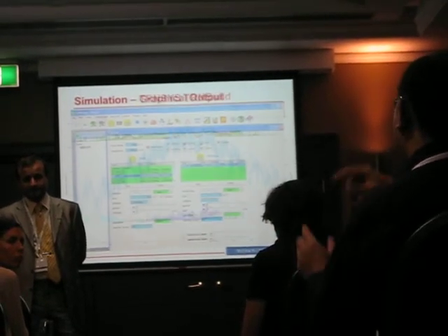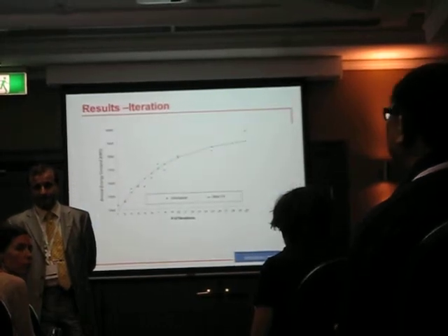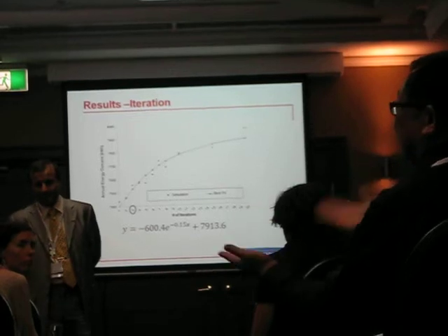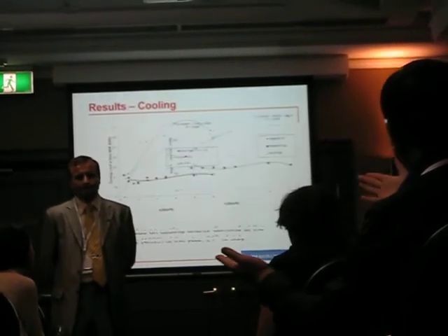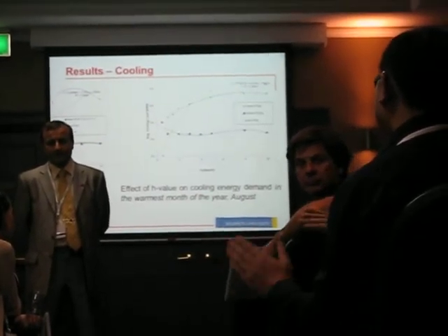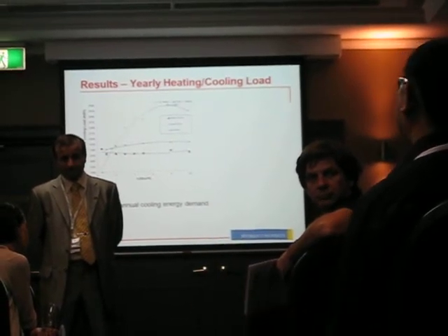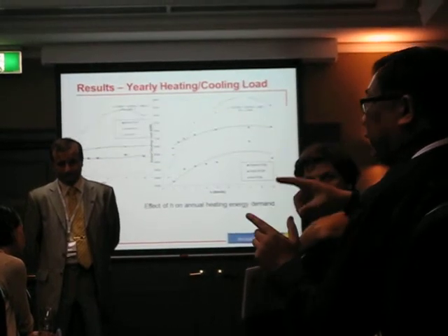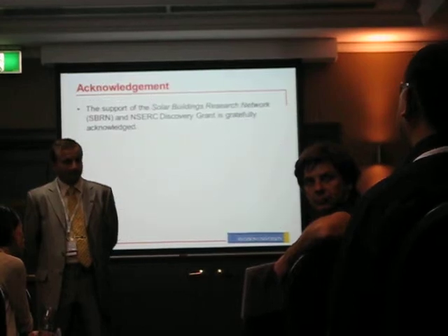If you're doing hourly heat release, heating load or cooling load, that will be different. Because in the long run, you totally have that total heat of fusion, your potential heat that will be released totally. So for the yearly energy consumption, it won't have any effect at all. But for hourly, that is instant energy consumption, definitely it will have some effect.